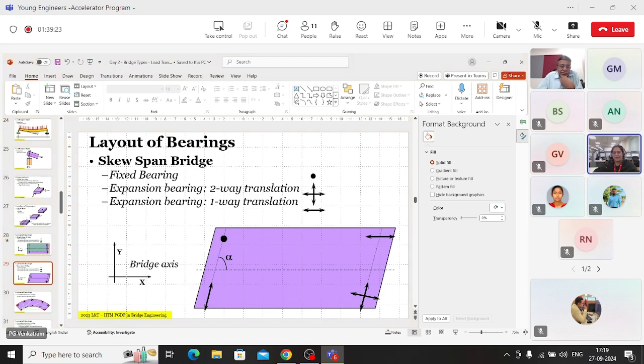But the long direction restraint in the free bearing is somewhat skewed in the other direction. No. See, what does that mean? That double arrow literally means it's free in all directions. Free bearing means there is no restriction. It is not as if it's guided in those two directions only. No, I think you have misunderstood that symbol. That symbol means it's free in all directions. So will there be stresses due to that arrangement in a skew bridge deck?